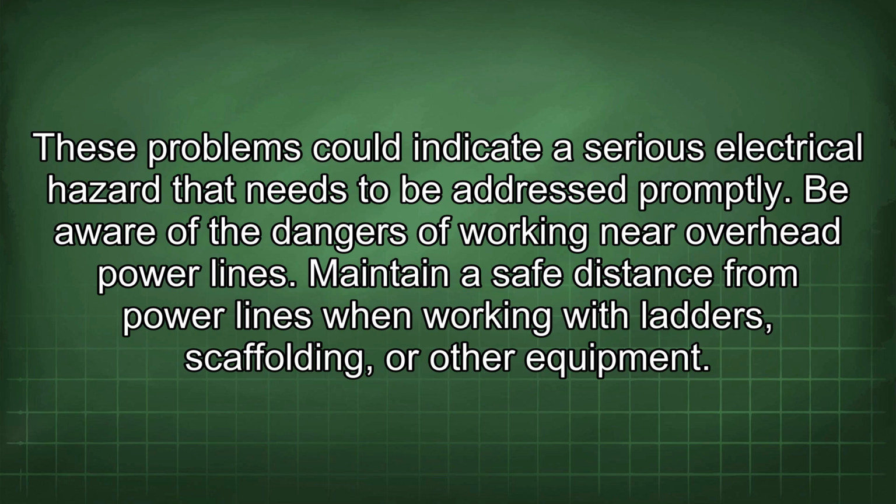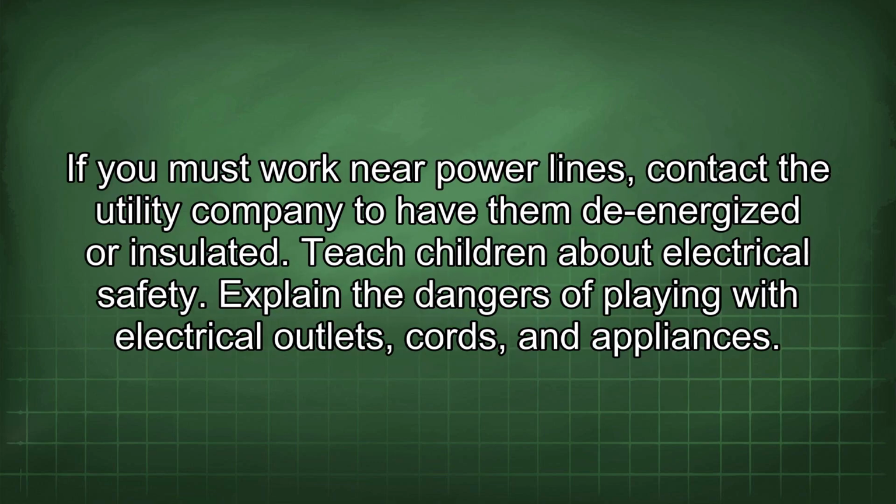Be aware of the dangers of working near overhead power lines. Maintain a safe distance from power lines when working with ladders, scaffolding, or other equipment. If you must work near power lines, contact the utility company to have them de-energized or insulated.